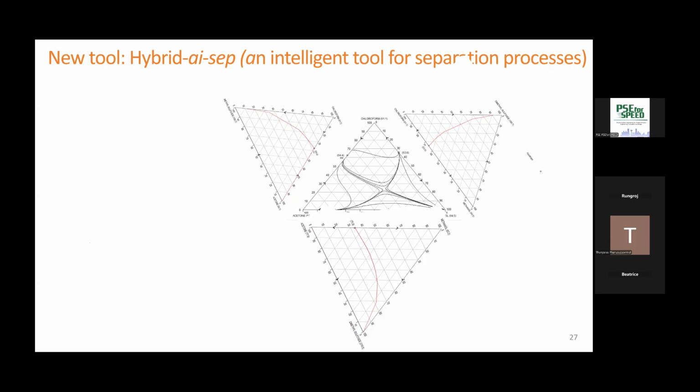So how to take one compound out, which would leave the other 2 compounds with its azeotrope, but that azeotrope is easy to separate. So if we can find a way to remove one compound so that the other 2 compounds are easy to separate, one would be by distillation, by solvent-based extraction. So we need to find a solvent. Another could be to use a membrane to take one compound out.